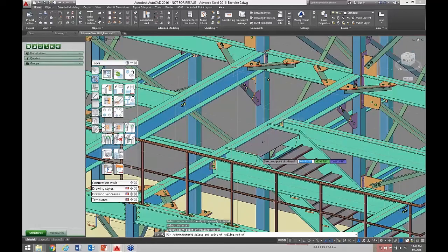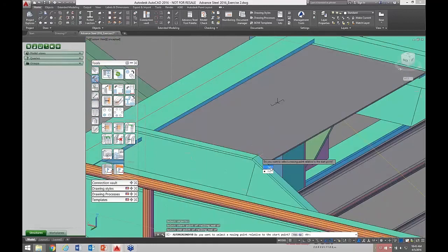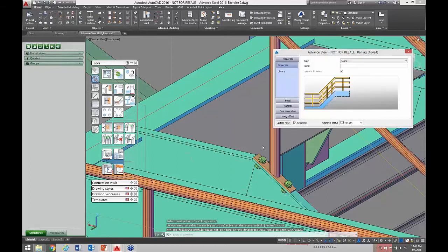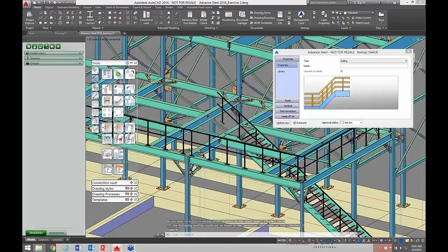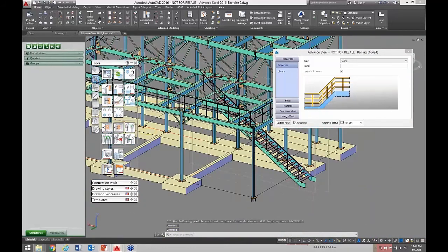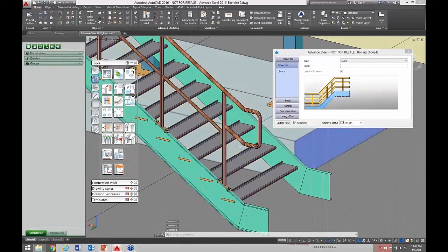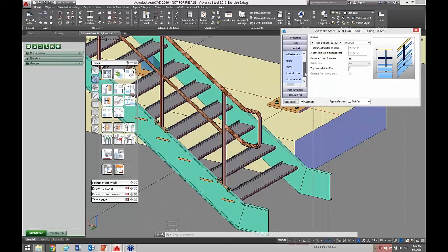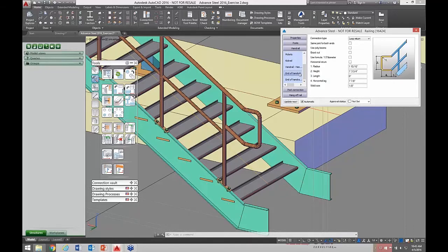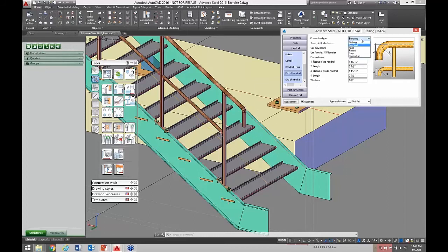I'm just going to simply pick these, and we'll see what we're getting for this slope condition. Again, similar fashion to what we looked at. Now I picked so far, that's why it's extending, but I can make alterations to that. Let's note at the bottom landing that we're going to have the capacity to affect that end rail condition for the handrail, whether it's a return, a bend, or a loop condition, whatever that may be, all dependent upon those reference points that I gave it.